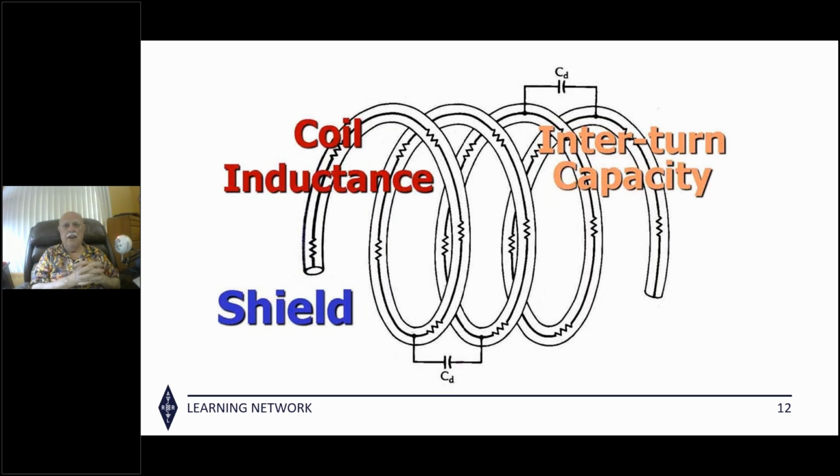If you're trying to feed an antenna that isn't 50 ohms, you need some kind of impedance transformation, such as with the off-center fed dipole, which is a lot of 400 ohm impedances up there. So the 4-to-1 balun, if it's a 4-to-1 ferrite balun, will usually perform both functions for you. It will choke off the current and will perform the impedance transform.